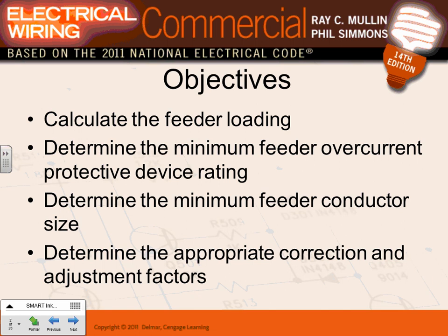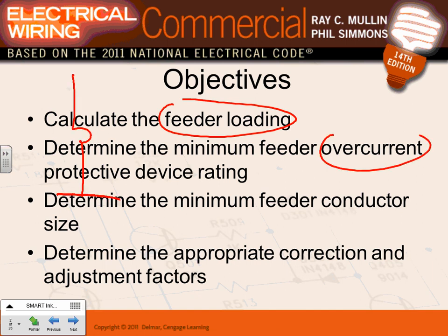Okay, feeder loading. We'll talk about feeder loading and feeder calculation. Determine the minimum overcurrent protection device. So I have my feeder here, and my feeder is feeding a panel, and you guys are going to size the conductor and the overcurrent protection device. That's what this is supposed to do. Determine the size of the feeder conductors and the overcurrent protection device. Determine the appropriate correction and adjustment factors, based on bundling and temperature.